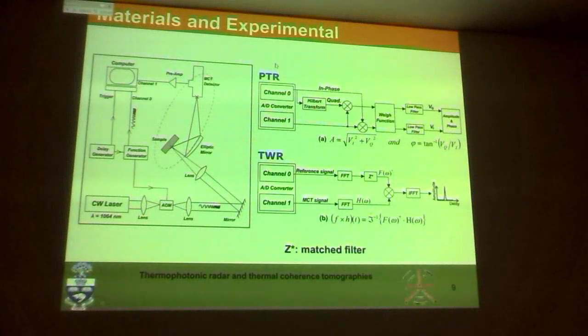Mercury cadmium telluride detectors started out long, long years ago. Primarily they were essentially DC, but then they started going into the AC mode. You can get megahertz infrared detectors right now. They're very fast. They are very much centered in spectral ranges, so depending on the spectral range that you want, you can get a parameter that's called detectivity.